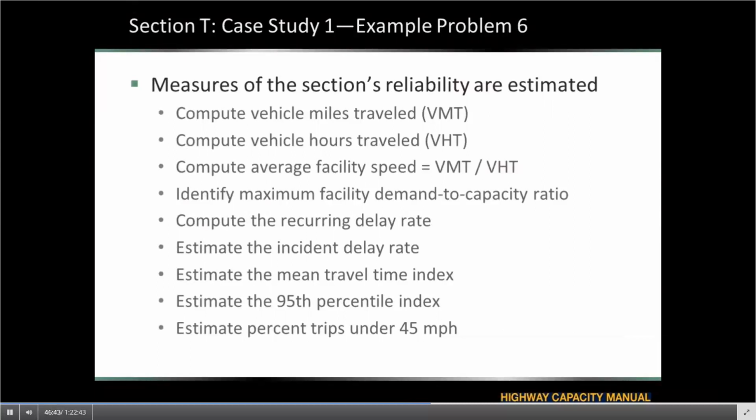those particular travel times, but an addendum to the guide, which is available online in volume 4, in the same place where you can download the guide itself, provides information on estimating the 50th and 80th percentile travel time indexes, from which the level of travel time reliability can also be estimated. The method for calculating these measures comes from the same source as the method presented in the guide for calculating the mean and 95th percentile travel time indexes.